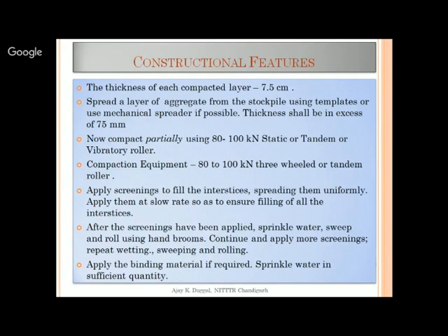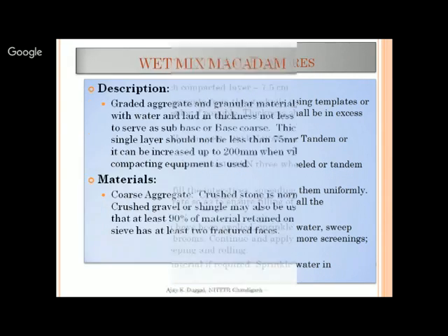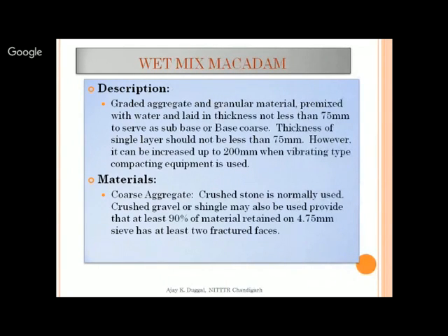So water bound macadam construction is very useful if it is done in a controlled manner. But remember the application is manual, so that is why it is time consuming. अगर आपको प्रोजेक्ट को जल्दी खत्म करना है तो वाटर बाउंड मैकेडम जो है वो टाइम कंज्यूमिंग एक्टिविटी है. तो उसका अल्टरनेटिव है वेट मिक्स मैकेडम, WMM. Wet mix macadam is a granular material pre-mixed with water. Pre-mixed with water यानी पहले से ही आप पानी में मिक्स करेंगे उसको साइट पे लाने से पहले.